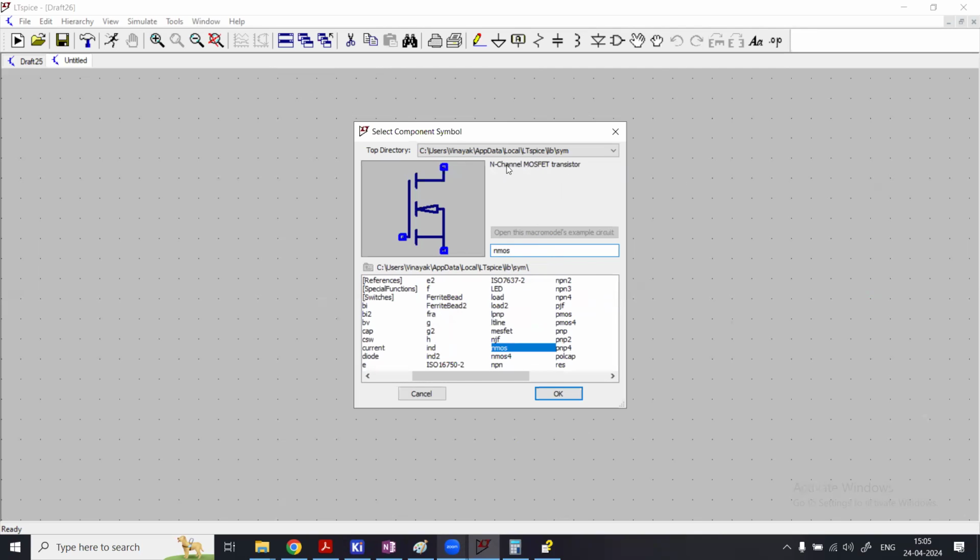With that type, you see that there is this N-channel MOS transistor, whose body is tied to the source pin of this transistor. For the PMOS, where is the PMOS here? Here. Here also the body is tied to its source pin.